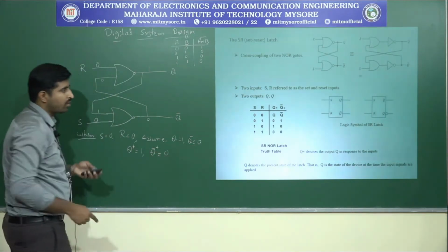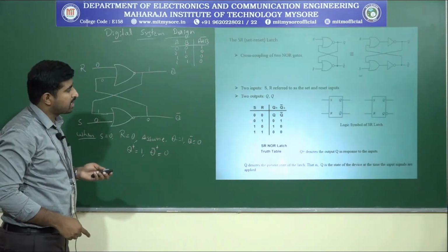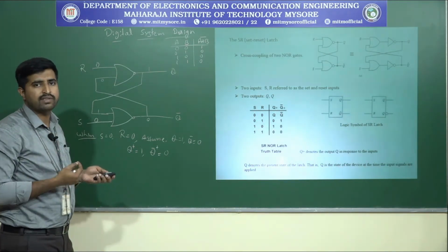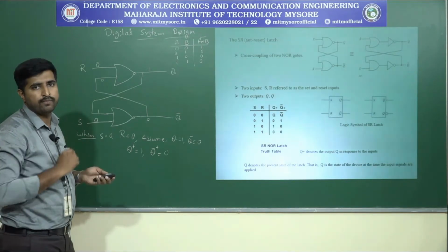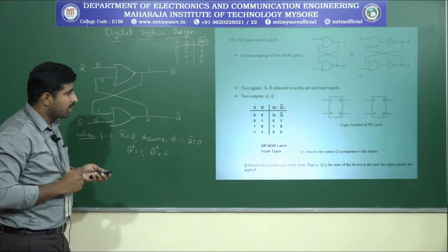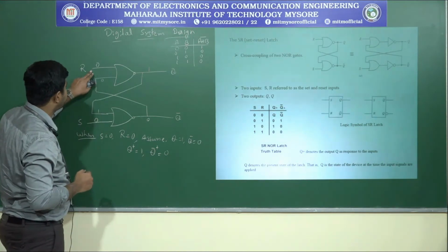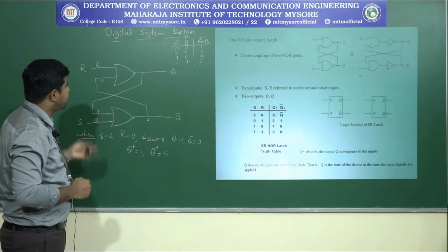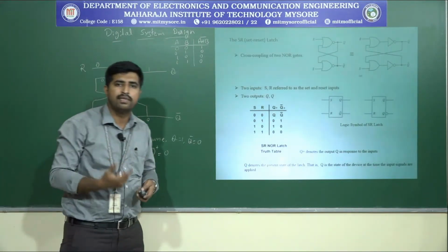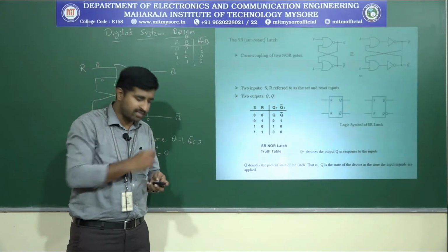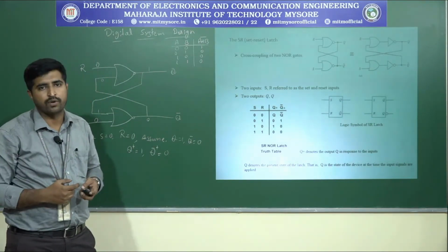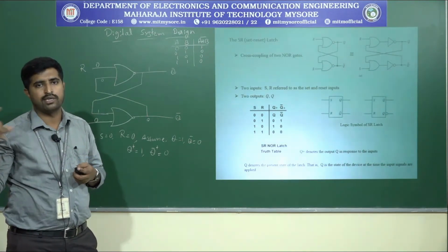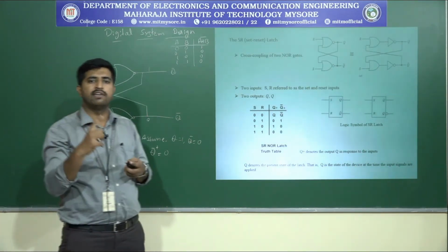So that's why we write that when you are giving the inputs S and R as 0 0, it will retain the previous state. Whatever the state is, that will be continued. So that is the output when the inputs for the SR latch are 0 0. This state is called similar to a bistable state, as we discussed previously, because it will maintain a constant, stable output when the device is turned on.